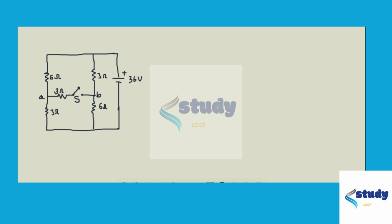Now when the switch S is open, no current flows through this 3 ohm resistor, so it seems like there is nothing in the middle. So there are only 6, 3, 6, 3. These four resistors are the only ones available to take the current that comes out from 36 volts. The current sees two branches. One branch has 6 and 3 in series, and the other branch also has 6 and 3 in series, so both have equal resistance.